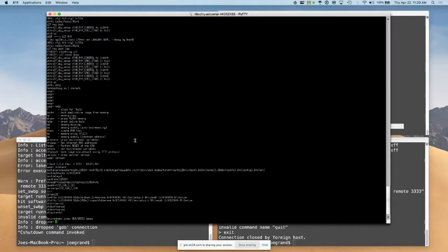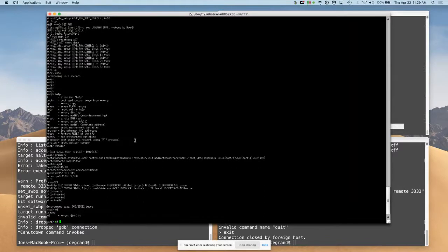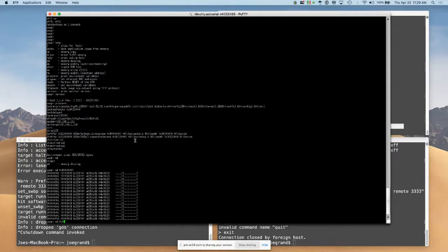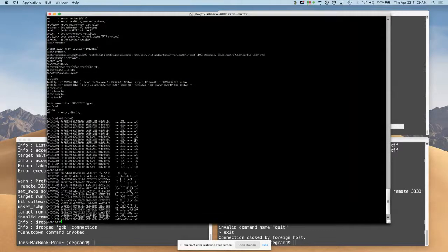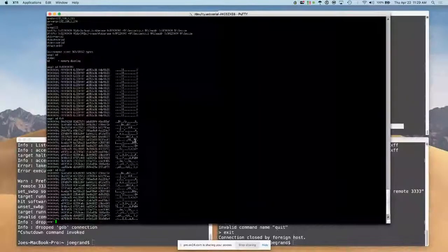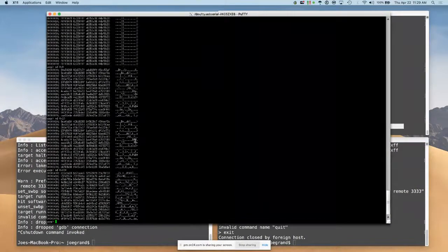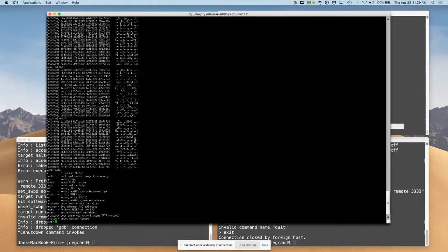We can also display memory, which is kind of cool. So let's try. It looks like I think memory starts at 8. I don't know. I'll just pick a guess, 8 million or something like that. Nothing useful there. How about at address 0? So we can go through and actually view different memory address locations. So this might be something where maybe we manually go through and dump the memory this way if we want to. There are other ways to do it, like I'll demonstrate. But just the fact that we can do all of this through a very simple UART interface is pretty cool.